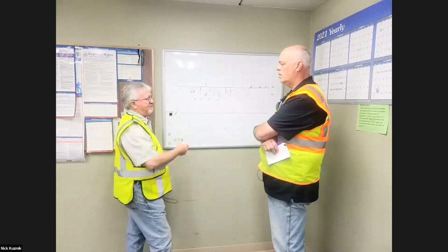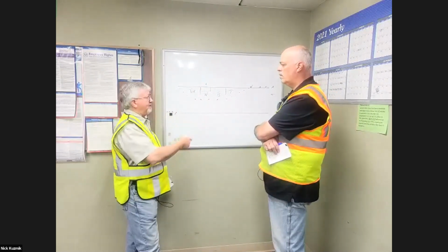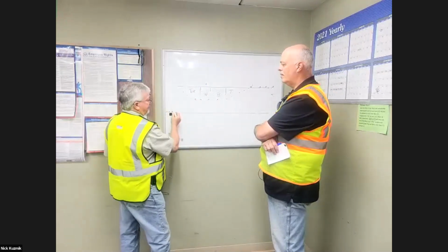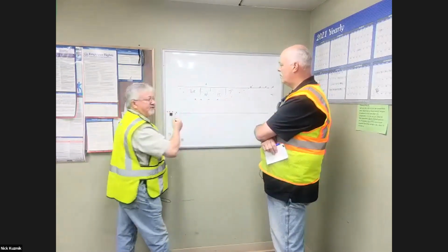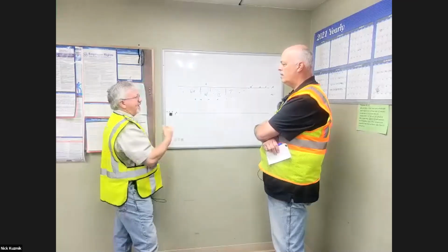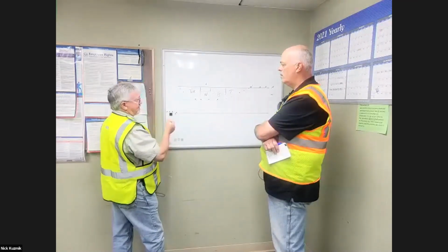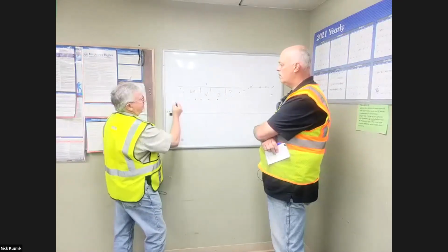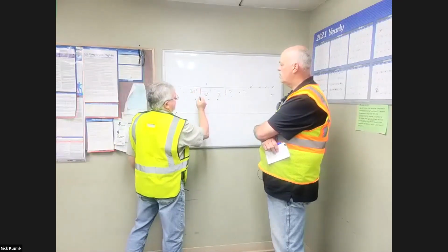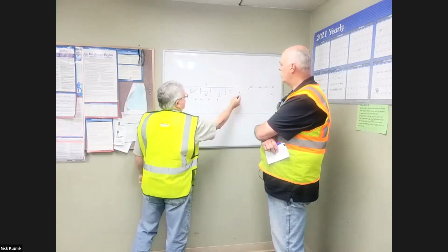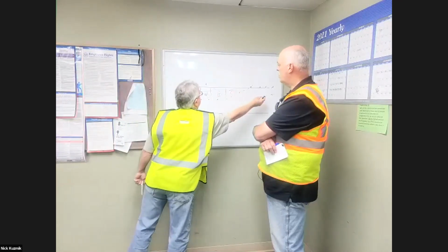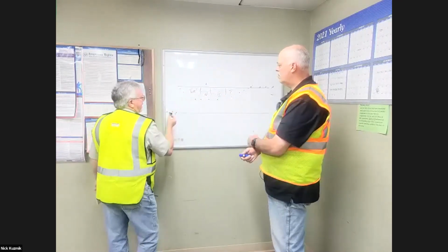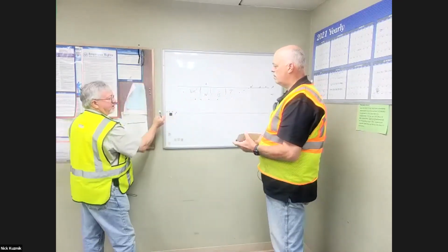The flagger's job is to protect the people in the work zone. So ideally, you're going to have some sort of direct communication, whether it's visual or a horn or something like that. Again, it's going to depend on your work zone itself. So these are the 5 sections that you're really going to have: your sign zones, taper, buffer, work zone, termination zone, and then again, your flagger and work signs.